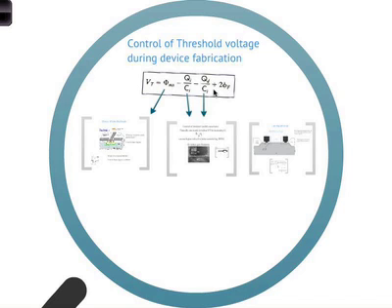The Qd is the depletion charges. You have to have a depletion region, so you have to have some voltage drop there. And 2 phi f is the band bending for strong inversion. So those are the terms you can control. Now, if you think about it, you can control that. We already saw that by the doping of the substrate, right? That's basically the phi f, essentially the distance between the intrinsic level and the valence band for the p-type substrate, or the conduction band for the n-type substrate. But it turns out you can control these other things as well.